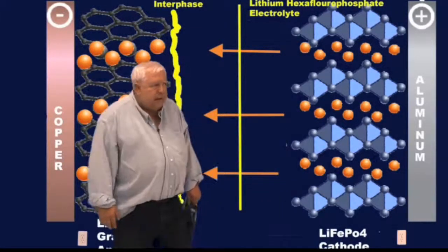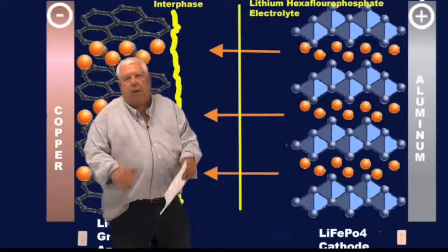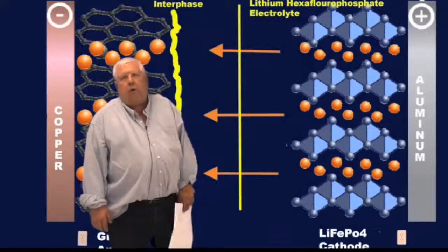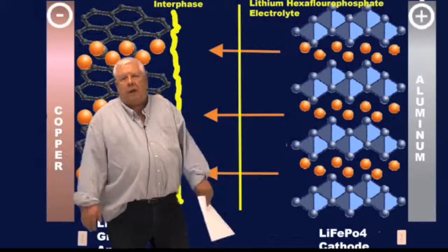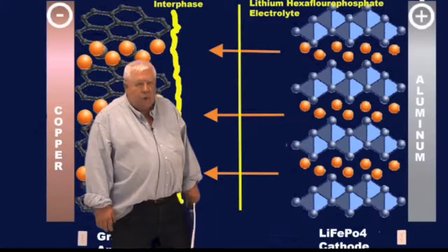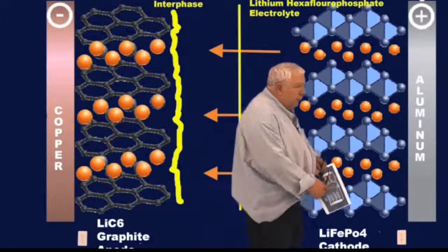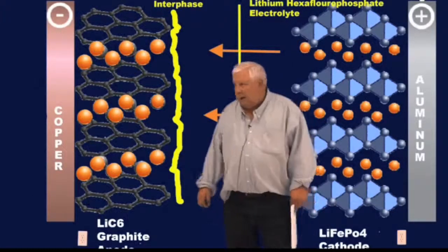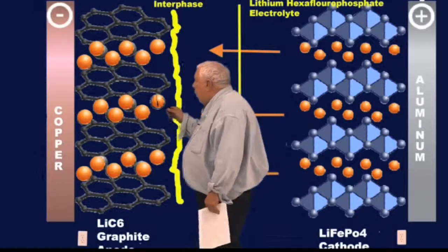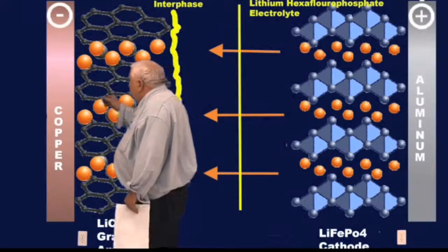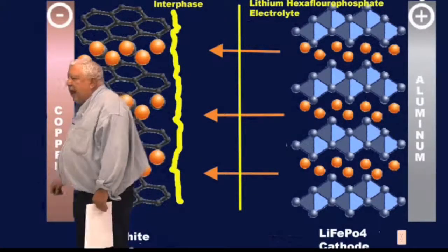Now you understand that all these foils are in parallel, and so that will also start to discharge all the other cells. And we can get very quickly into a thermal runaway situation that not only shorts the cell and causes high currents, but blows up our SEI layer,